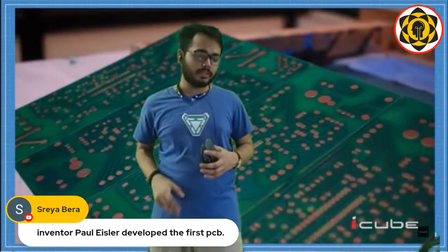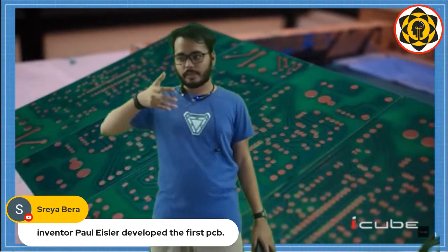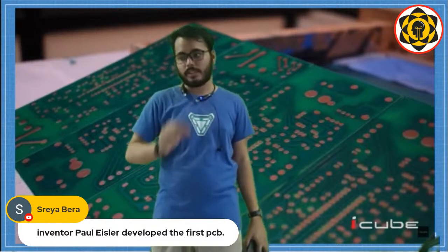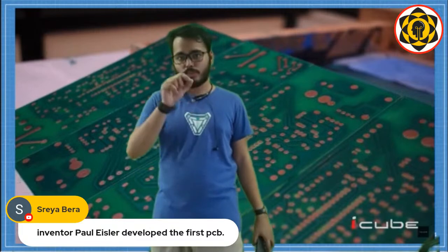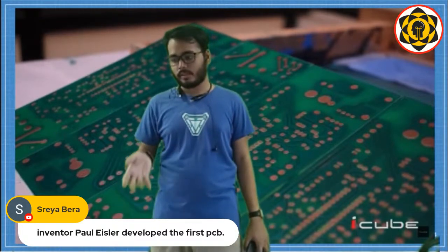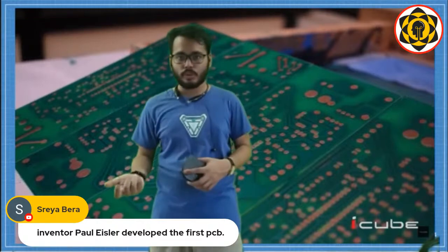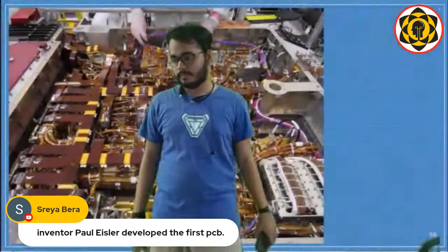So now, as you guys can see, it's totally ready. Our PCBs are ready. Now all you have to do is take a small drill bit, not the big drills, and poke a hole wherever you want to place a component. For through-hole components, you poke a hole in there, and wherever you want to place an SMD component, there is no hole required. You can directly solder onto these copper patches. So yeah, this is the stuff.